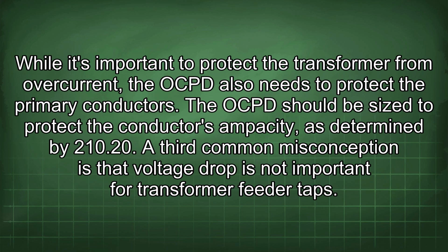While it's important to protect the transformer from overcurrent, the OCPD also needs to protect the primary conductors. The OCPD should be sized to protect the conductor's ampacity, as determined by 210.20. A third common misconception is that voltage drop is not important for transformer feeder taps.